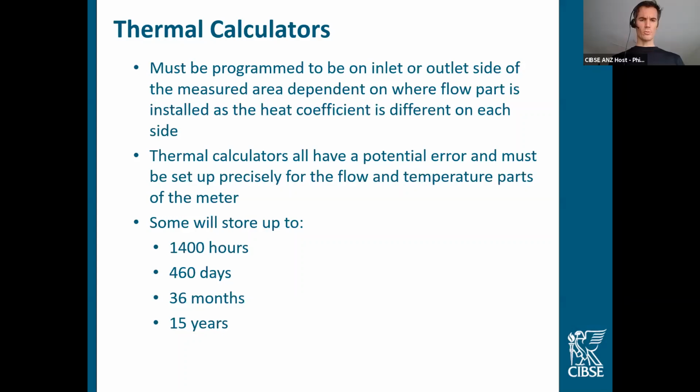Surely that temperature would be almost identical within a short reach of the inlet or the outlet side of the meter. Oh no, because it could go off and cool, it could be on a whole hospital wing and it might come back 10 degrees cooler, and the K factor would be significantly different. Well, in relative terms. Sorry, yeah, no, you're right. So you take a heating application, it could go out at sort of 60 degrees and come back at 30, or as in our example before, maybe it comes back at 55, depending on how much heat is taken out of that water.